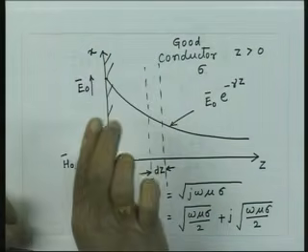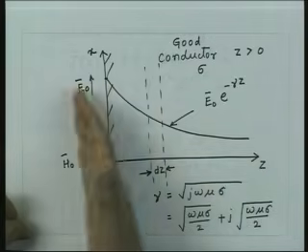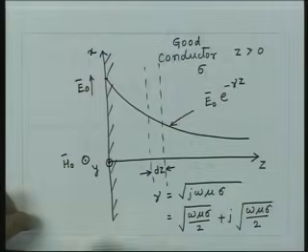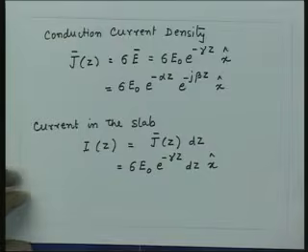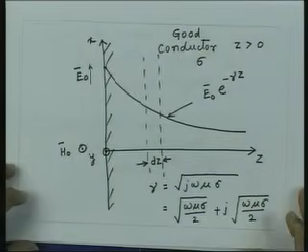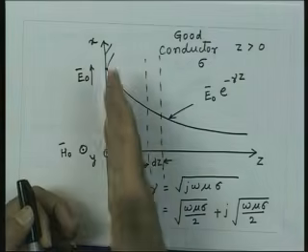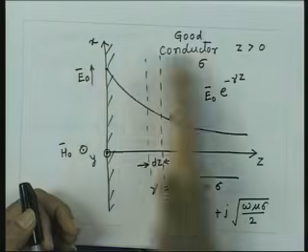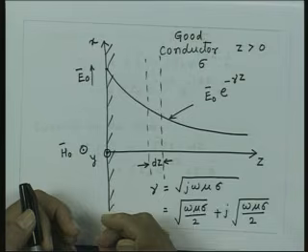Then, as we mentioned, now we want to find out what is the current which is flowing under the area which is unit area in this. That means, per unit length in the y direction, how much is the total current flowing under this surface. So, we integrate this in the z direction. So, we get the total current, and that current we call as the surface current. Now note here, there is no true surface current, the current is actually flowing in the depth, and actually it is theoretically extending up to infinity.